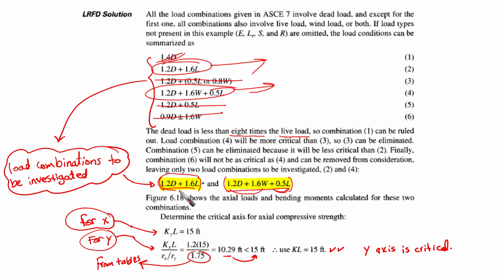Here we are not expecting any lateral translation because our loading is symmetric and the geometry of the system is symmetric. So we are going to find no amplification needed for global buckling. However, here we are already having some load. Sorry, the load that is gravity load is 0.5 L and 1.2 dead, and this is the one that is related to the translational.